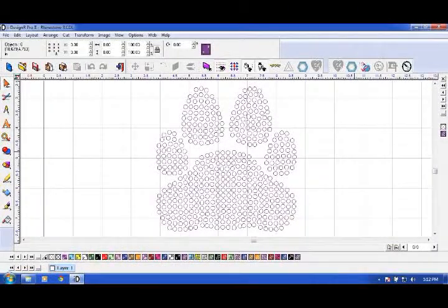The next button has to do with replacing rhinestone shapes. Here's a scenario. You have a rhinestone design pattern that has been imported from another application. You like the pattern, but would like to replace the rhinestones with a different size and color. Or you'd like to replace them with rhinestones found in the library. This is where the next function, Replace with Rhinestones, can be used.